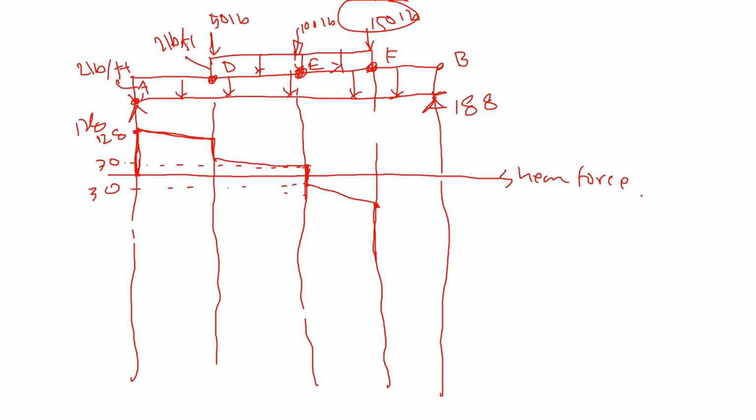So this 150 drop here like this, and then slide drop here. This thing is definitely not drawn to scale. So I think this was 188, and this was something I can't remember, 186. So this was 186. So this is the shear force diagram of this bicycle problem.